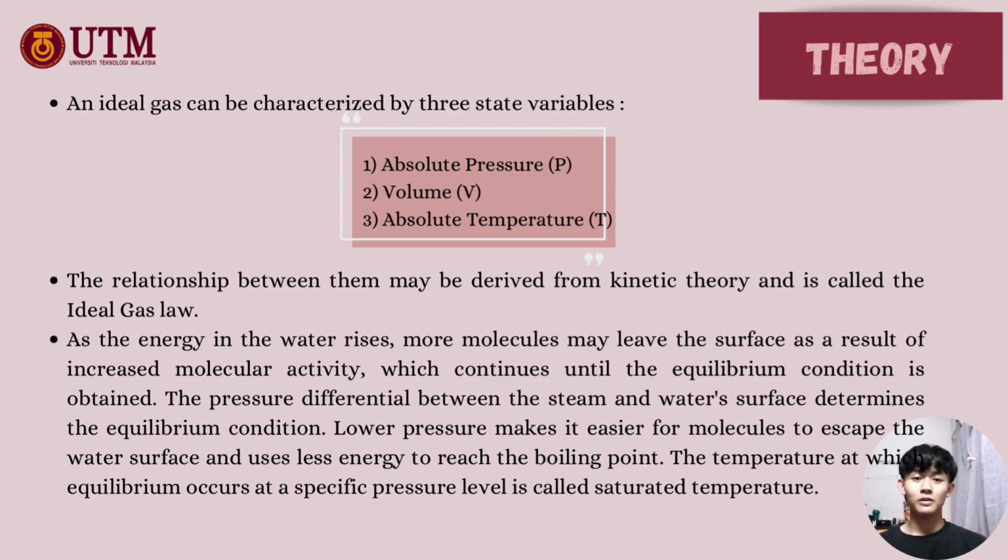As the energy in the water rises, more molecules may leave the surface as a result of increased molecular activity, which continues until the equilibrium condition is obtained. The pressure differential between the steam and water surface determines the equilibrium condition. Lower pressure makes it easier for molecules to escape the water surface and uses less energy to reach the boiling point. The temperature at which equilibrium occurs at a specific pressure is called the saturated temperature.